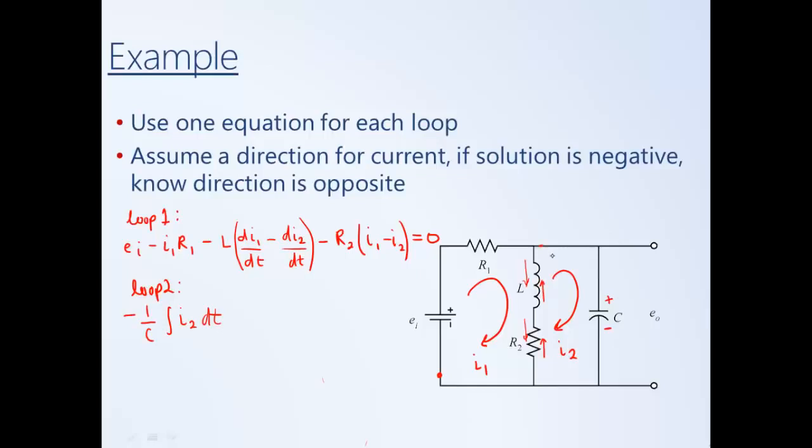So again, I started here where I defined this to be ground, or R0. We dropped across the capacitor, then we continue around the loop and we'll drop across the resistor R2. Where again, in this case, I have I2 flowing up through the resistor and I1 flowing down through the resistor.